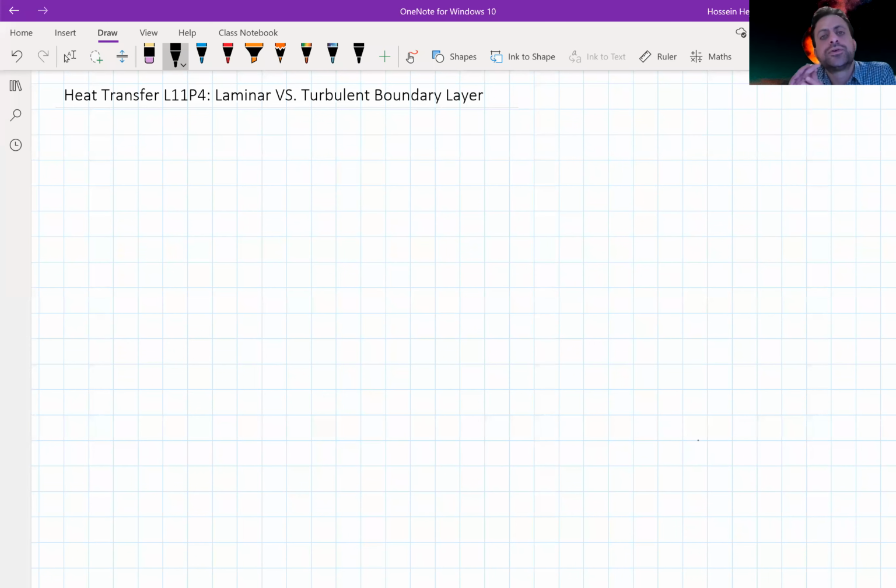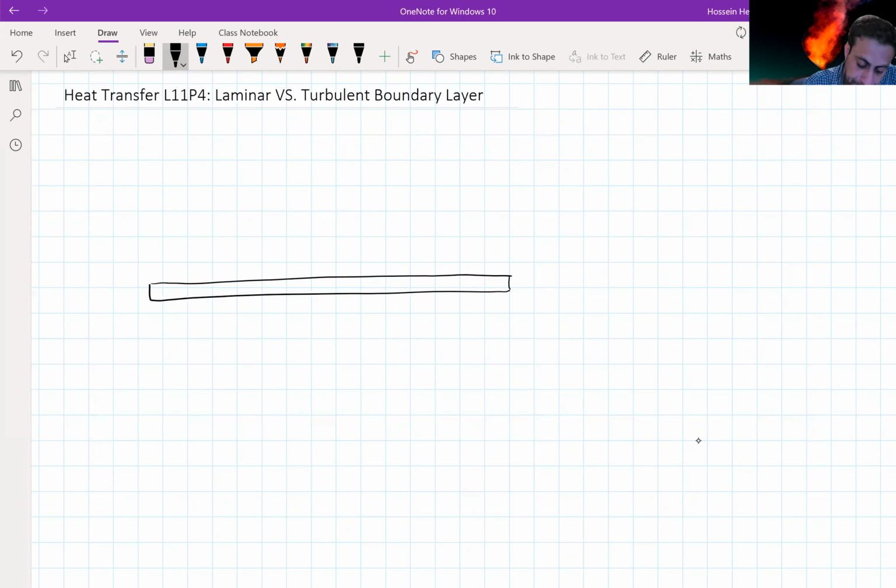On fluid flow over a flat plate, both laminar and turbulent regimes can occur. If we have this flat plate, let's say there is a uniform flow with U infinity passing over this region. Initially we can have a laminar flow at the beginning, at the entry, where in this laminar flow the velocity vectors are highly ordered, they are essentially 2D.